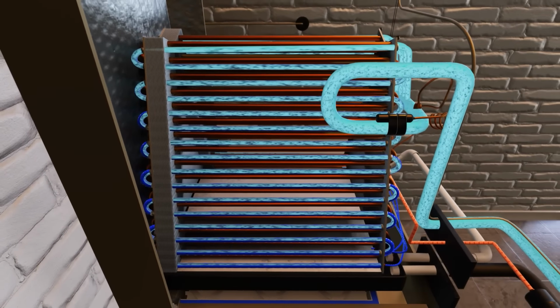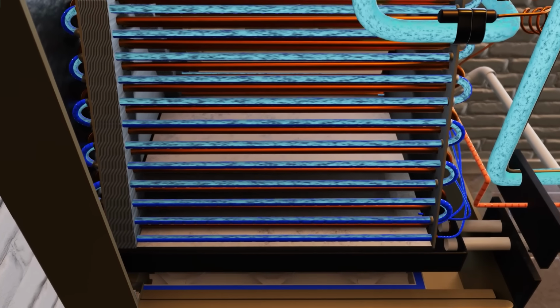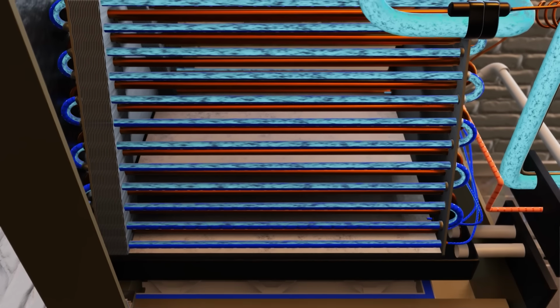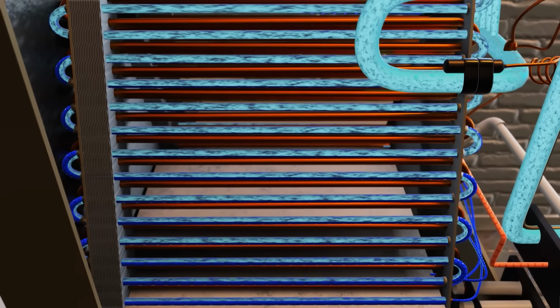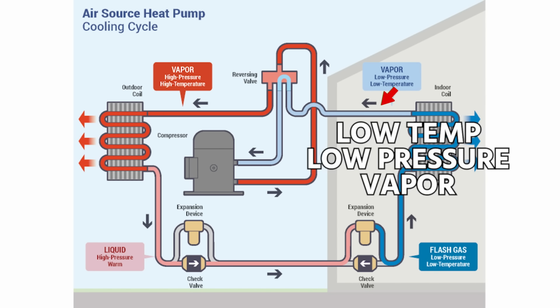So it acts as almost a heat sink, or it grabs the heat into that boiling refrigerant as it is low temperature, low pressure, expanding through that evaporator coil. The refrigerant enters the bottom of the evaporator coil and travels up and then leaves through the suction line. As it goes down through the suction line and back outside again, now it is a low temperature, low pressure vapor once again, headed back to the compressor.